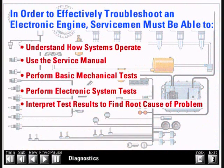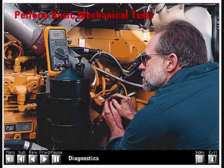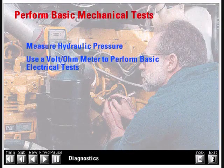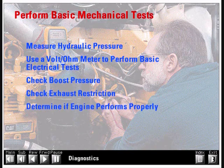The next important skill is to be able to perform basic mechanical tests correctly. This includes being able to measure hydraulic pressure, use a volt-ohm meter to perform basic electrical tests, and check boost pressure and exhaust restriction to determine if the engine performs properly.